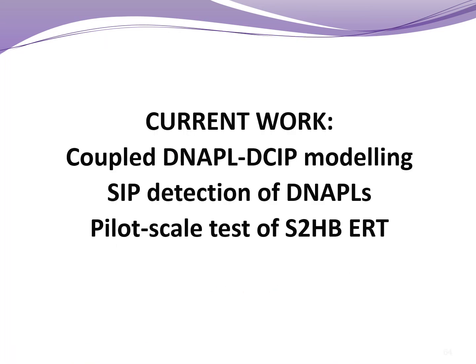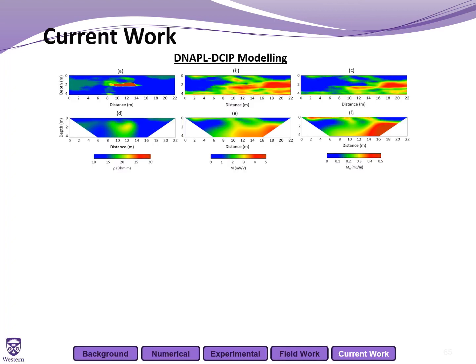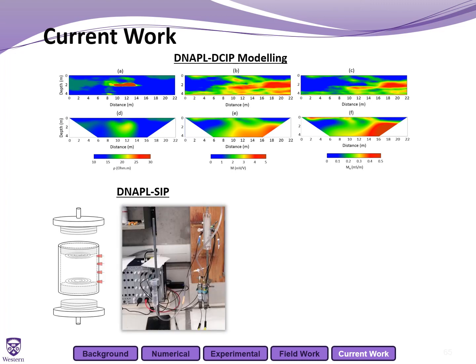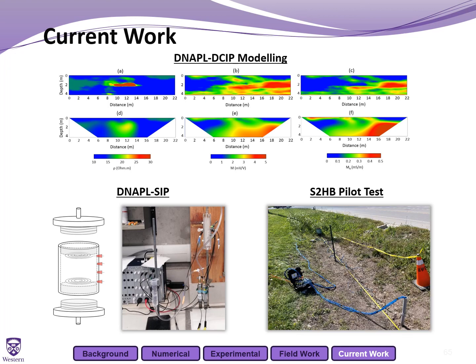So just to finish up, looking at the current work, some coupled modeling where again we're taking the DNAPL multi-phase flow model and now connecting that to time domain and frequency domain IP models. We're doing some DNAPL and SIP experiments, and also we're about to perform a pilot test at a field site with surface to horizontal borehole ERT.